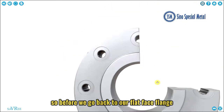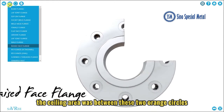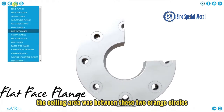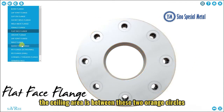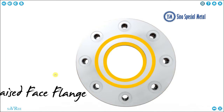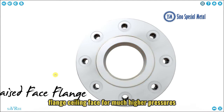So before, with our flat-faced flange, the sealing area was between these two orange circles. Now, if we go to the raised face flange, the sealing area is between these two orange circles. It's much smaller. That allows us to use this type of flange sealing face for much higher pressures.